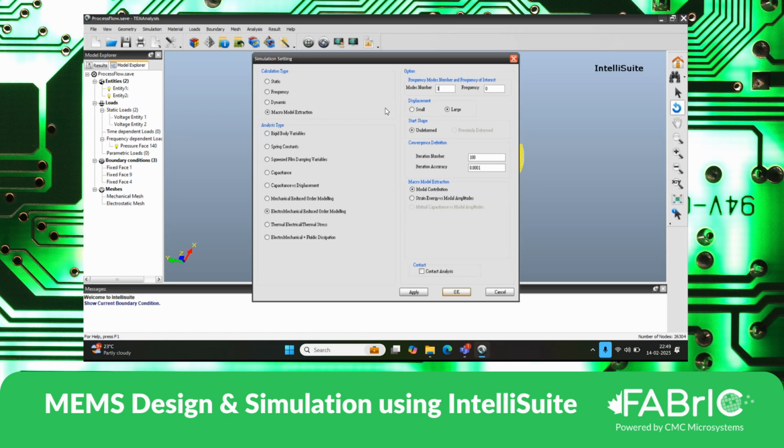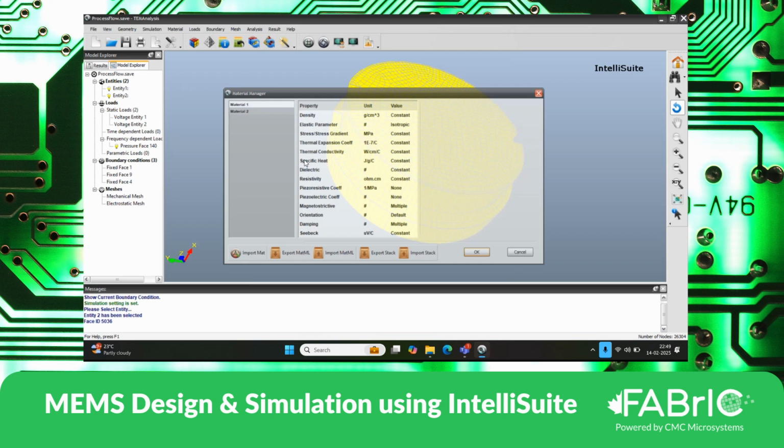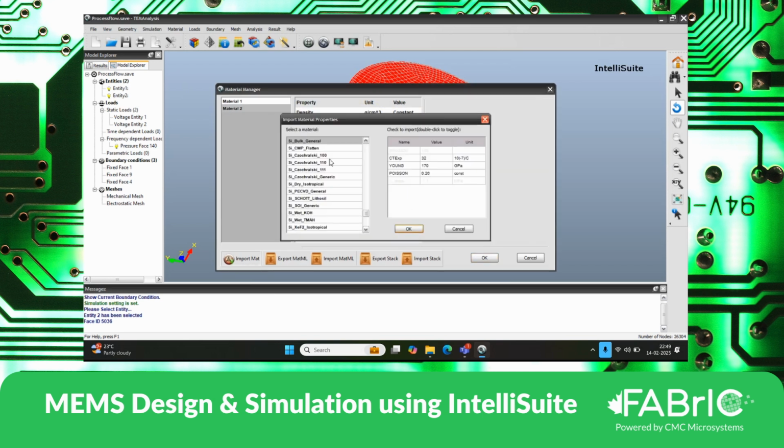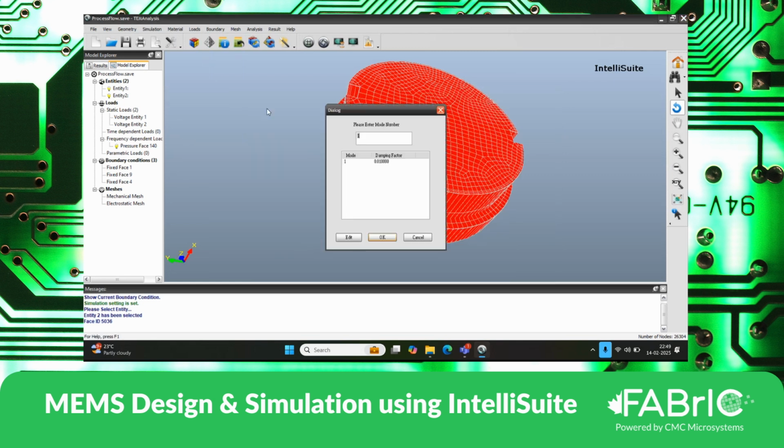Okay, so now at this stage, we apply and then click OK. Then material properties we have already defined in day 1. We just select the entity, the material database opens up, we import it, select OK, and then we assign it. Material properties are assigned.